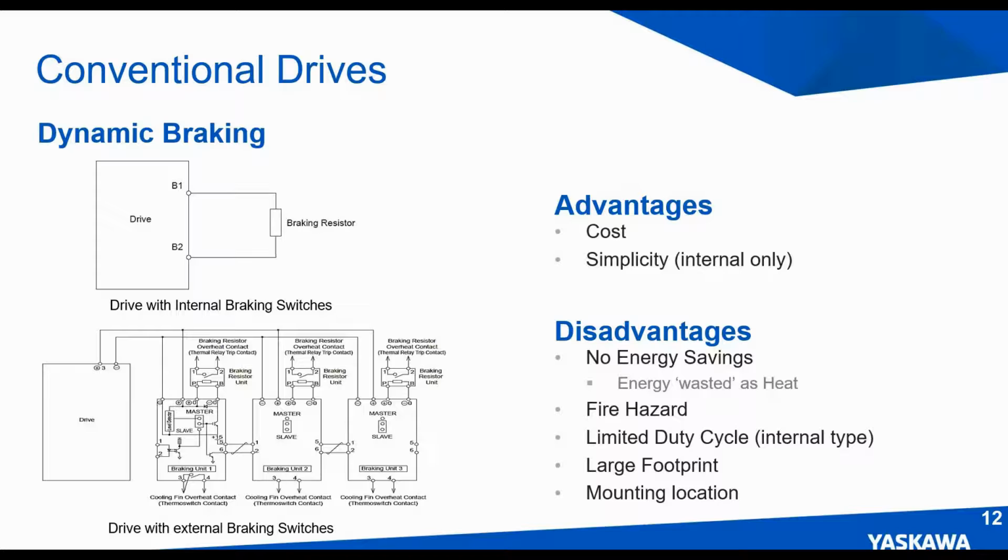Also, the drive's internal braking switch is limited in its usability. What do I mean by that? Usually these internal braking switches are typically rated for 10% duty cycle. That means these packages can get quite large and complicated, like the image below here, if you need large amounts of regen to be dissipated.